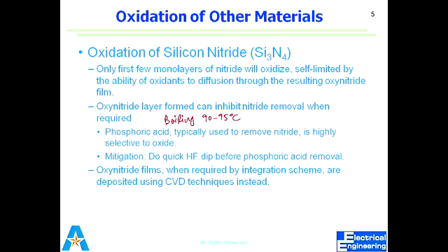Is oxynitride a better insulator than either the oxide or the nitride? Sorry? Is oxynitride a better insulator than only an oxide or only a nitride? For this, we should know the dielectric constant of oxynitride, nitride or oxide. But as far as I know, oxide is better than nitride. Nitride is actually the second option in industry after oxide, but oxide is still better than silicon nitride.